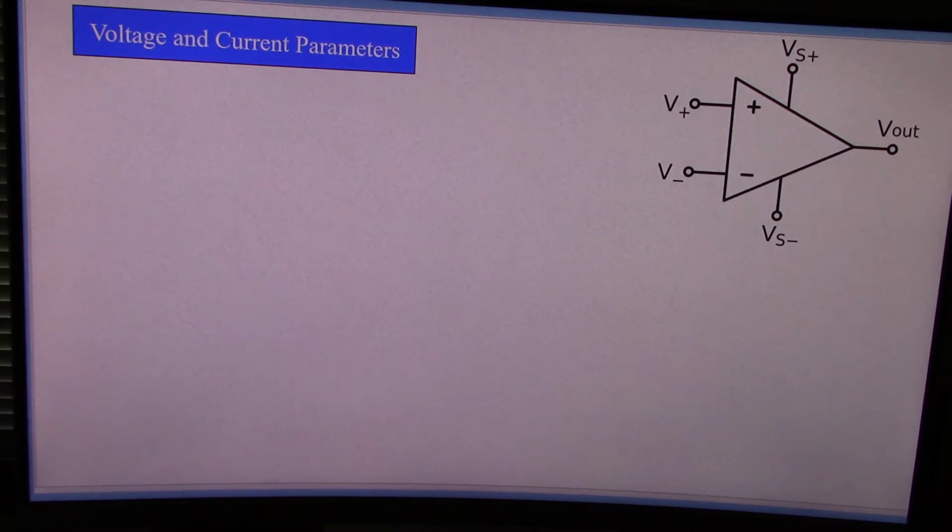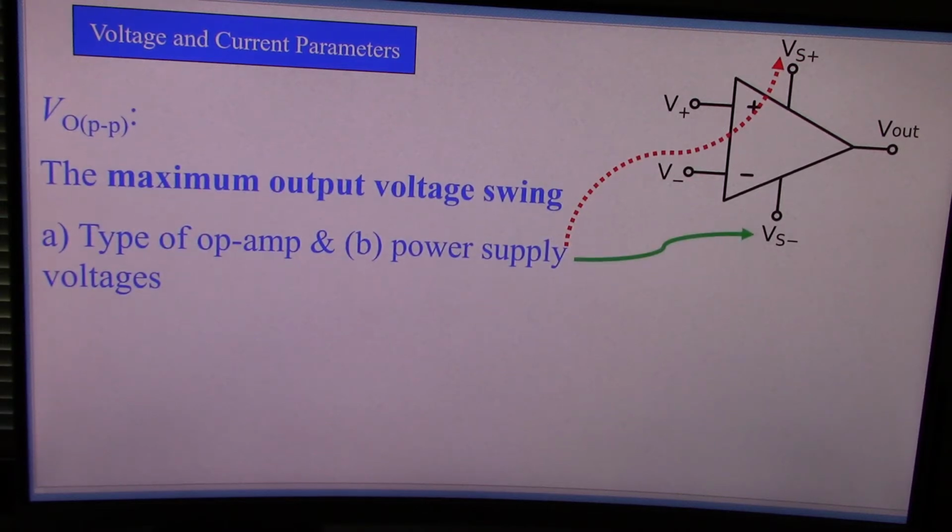So this is a typical schematic of an operational amplifier. What's interesting about this is that if this non-inverting input is bigger than this inverting input, the output swings to this voltage. Let me repeat that. If this number here is bigger than this number here, then the output swings to this. So that's kind of unique, because that's not what we've talked about with other devices before this.